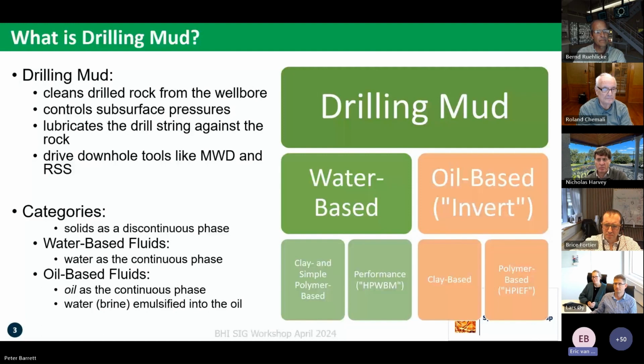That's quite apart from functioning as a conduit for wellbore logging tools, because logging in an empty hole is not so easy. Very broadly for us, in this discussion, there are two categories of drilling mud. There are the water-based fluids, where water or brine is the continuous phase, and oil-based muds, where oil or any non-polar solvent is the continuous phase.